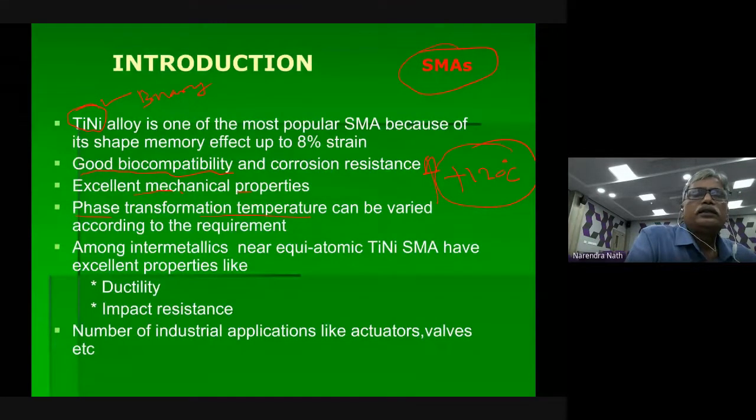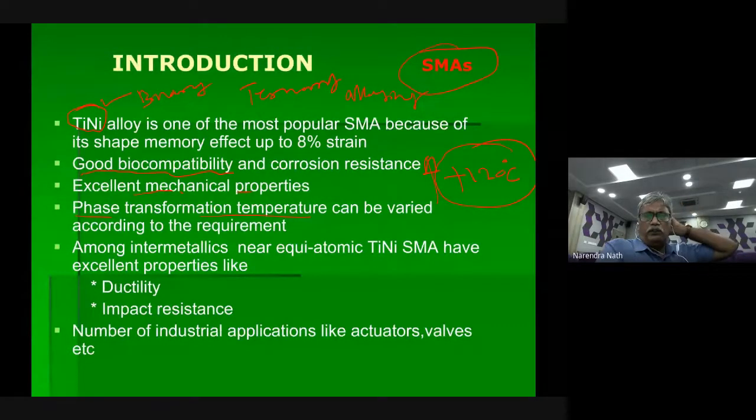Binary is nothing but only titanium and nickel. Or else, if I want to go for further lowering the transformation temperature, or further raising the transformation temperature, I have to think of ternary alloying elements. These alloying elements are available. Okay, if you see the literature, if you want to go for, say, 500 or 550 degrees, there are elements I can use as ternary elements.